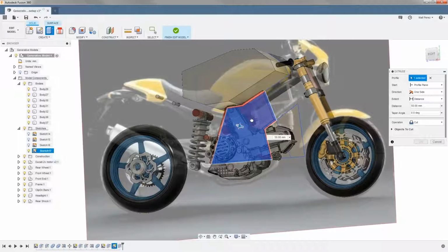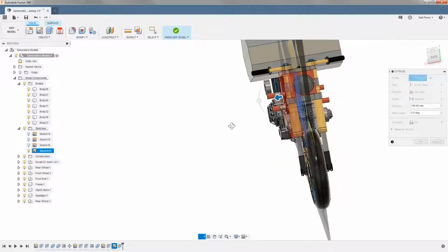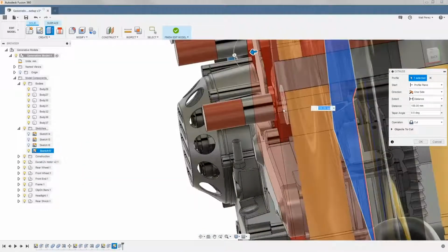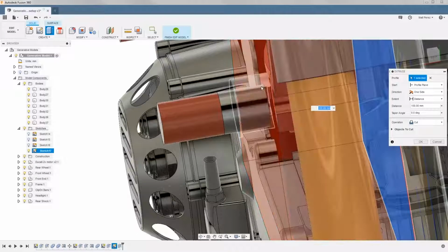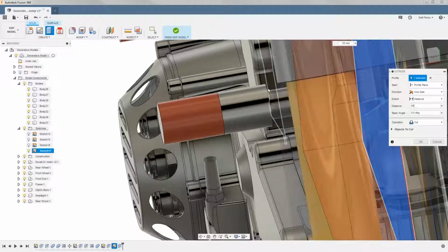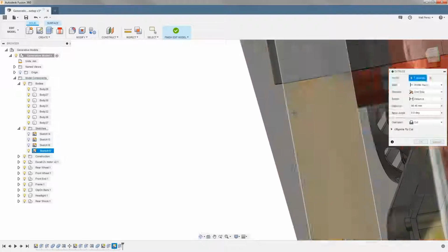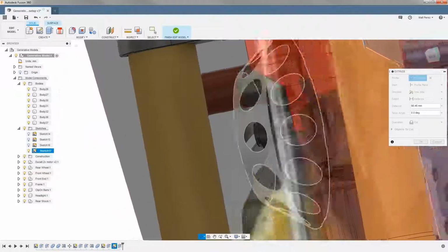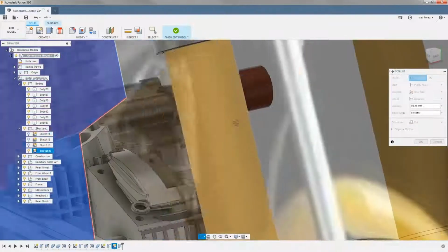And this is going to come out to the areas of our frame mounts. So we want to take it all the way to this edge here. So I'm going to just put that number back a bit, and I want to select this boss here. Now if you need to, again, we can hide geometry. Sometimes it can be kind of hard to select that face.